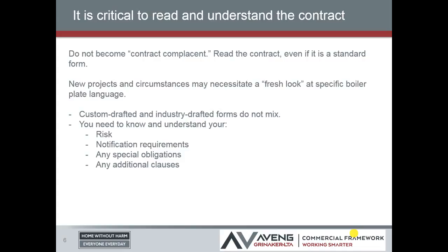Ground conditions, for example: if you're digging a deep basement on one contract and you hadn't got that on your last, you've got to be really aware of the provision of unforeseen physical obstructions and manage that extremely well, whereas it mightn't have been an issue on previous projects. So it's really important to sit down and look at the contract again at the start of the works and define what risks you really have to manage, particularly if you're looking at amended conditions of